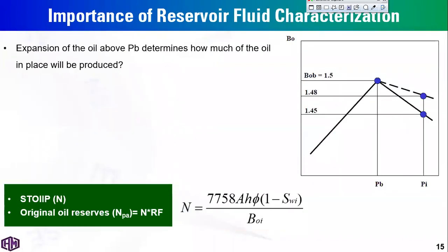As an example of PVT data application, the calculation of original oil in place, or stock tank oil initially in place, is calculated, as you know, using a standard equation as a function of the bulk volume, oil saturation, and this term which is a PVT parameter, the oil formation volume factor at initial reservoir pressure.